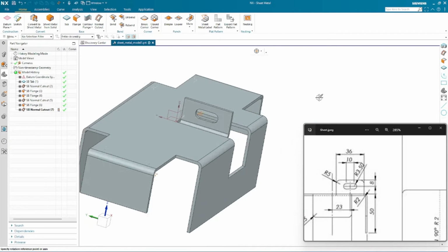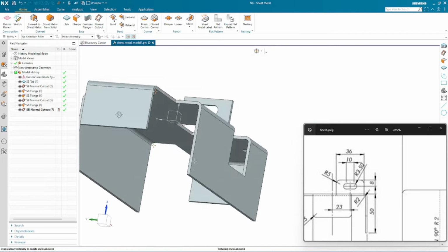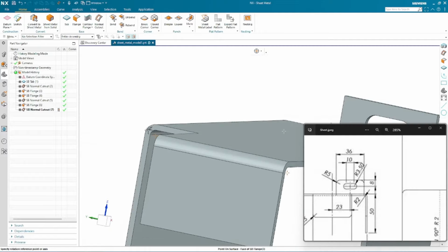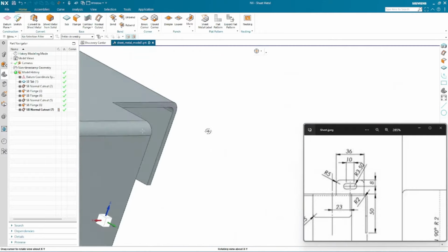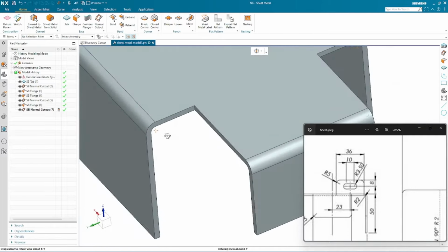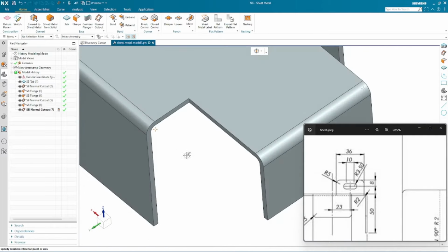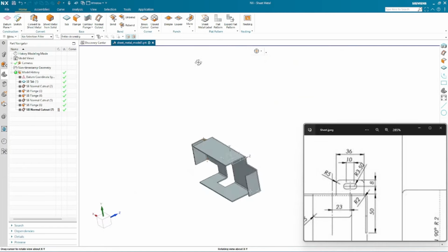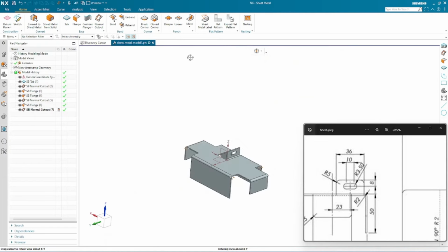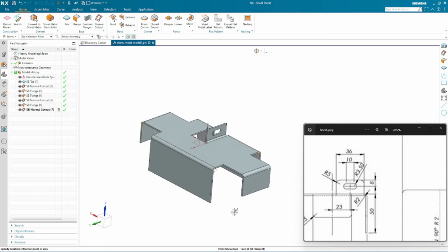Like if I want to rotate from this point, I will click and hold, and this middle point, the center of rotation, will be picked from here. If you do not click and hold middle click, then by default it will be selected at the center of the mass that we have created.